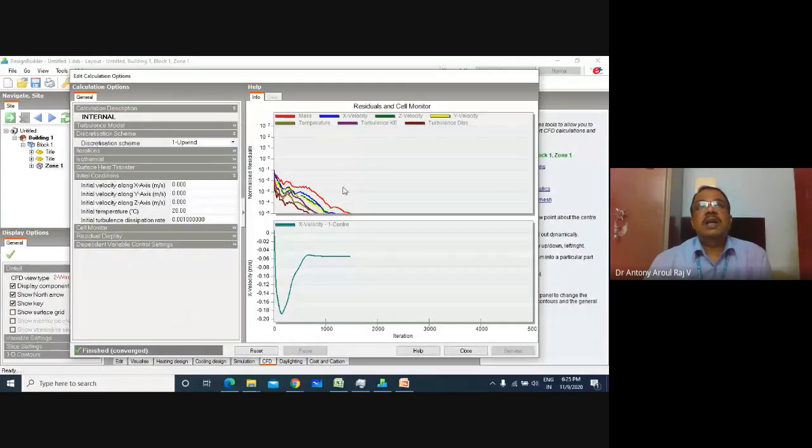Here it is given in the form of initial condition, but we are not solving a transient problem. We are solving a steady state problem. What is the meaning of that? It means you have to have the initial solution. Throughout the domain, I'm giving the x velocity, that is for the momentum equation. Throughout the domain, I'm giving the y velocity, so the y momentum equation. That means I'm giving a solution for the y momentum equation. Throughout the domain, I'm giving the z velocity.